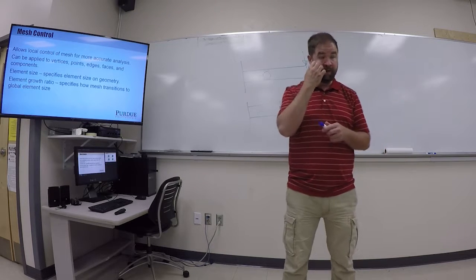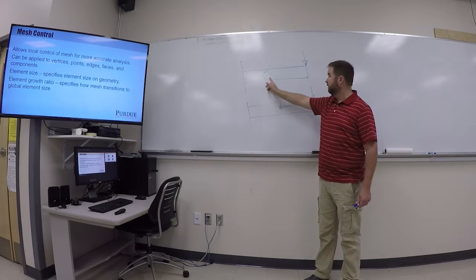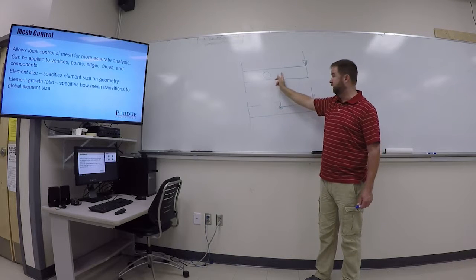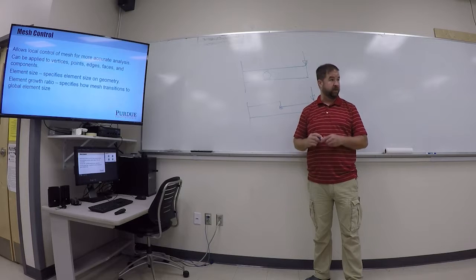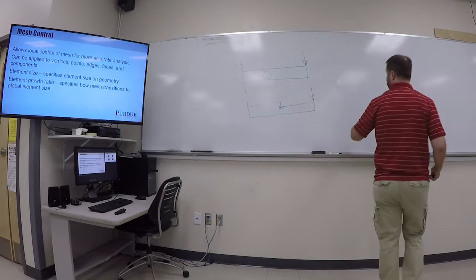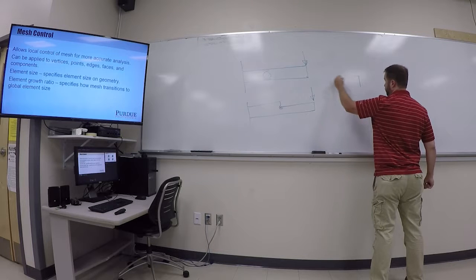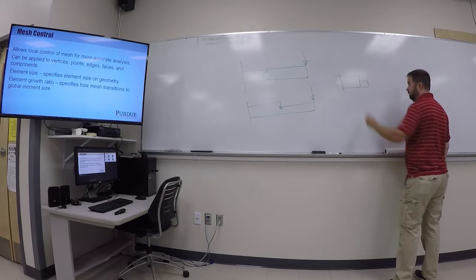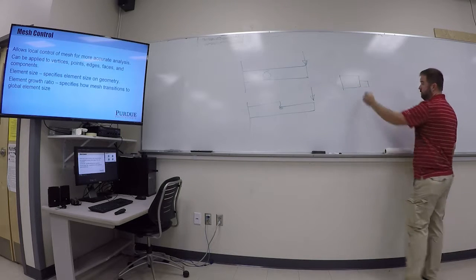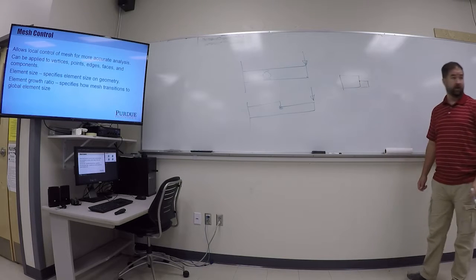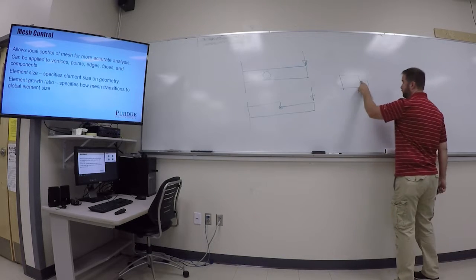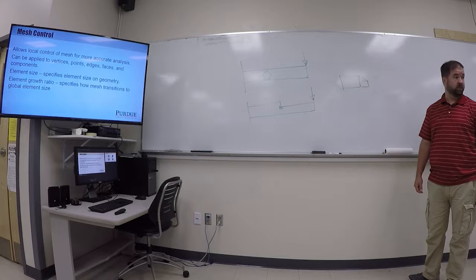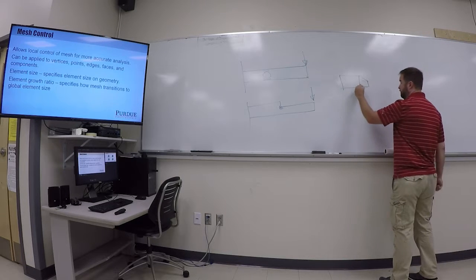Okay? So thinking about that, if I want to reduce the element size here, my triangles can't all be exactly aspect ratios of 1 because I have to transition in geometry. I have to get smaller and smaller, right? Okay, really simple looking at that. If I'm just using rectangular elements and I want to get to a smaller rectangular element, if I'm not using mid-side nodes, I can't do it that way. My elements have to start getting warped in order to make that transition, because the corners have to stay the same.